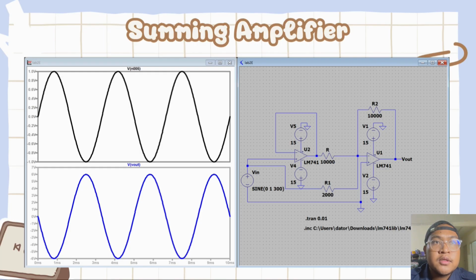Our interpretation of these results is fundamentally guided by core electronic principles, specifically the op-amp golden rules in the inverting amplifier and voltage follower with negative feedback. The virtual short principle is the cause that allows us to apply Kirchhoff's current law (KCL) at the inverting node.